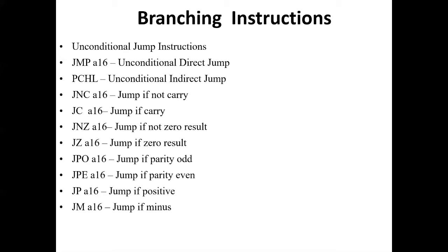Change in program flow is needed when a sequence of instructions is to be executed repeatedly. It is also needed when it is required to choose between two or more sequences of actions based on some conditions. The branch group of instructions in 8085 affects such a change in the program flow. The branch instructions can be used for affecting a forward branch or a backward branch.